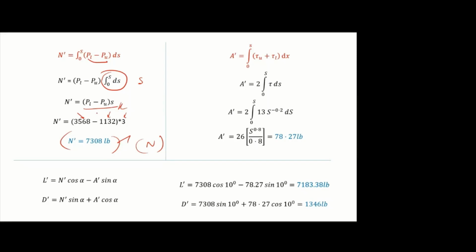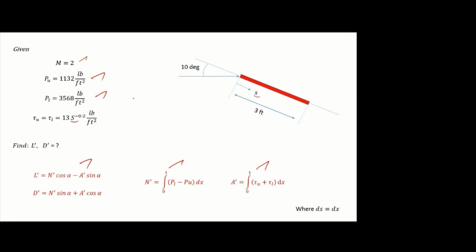Is that clear? It's not necessary that you go for the integration method. If you find that the values are constant, straight away you can find force as pressure into distance, that is, pressure into area. The difference will give you the force acting in this plane.